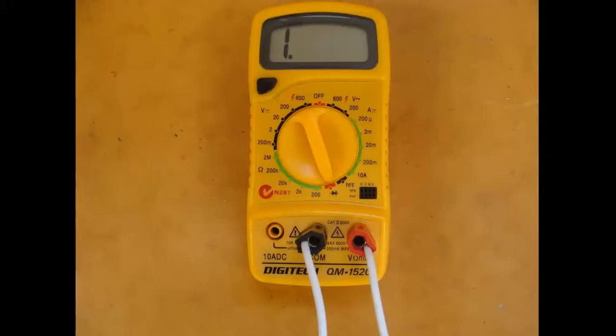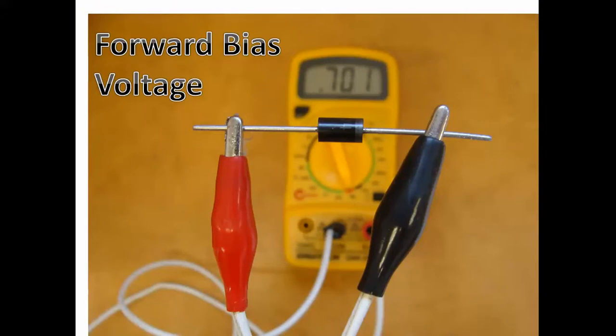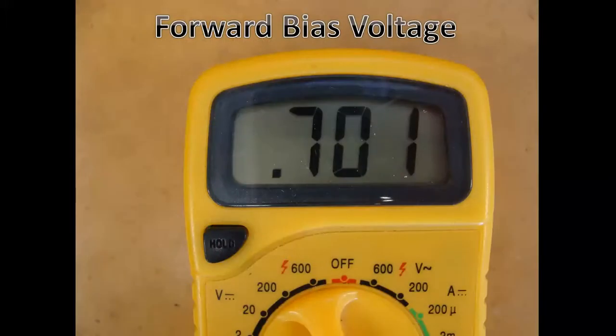We're then going to test the diode using the diode test function on a digital multimeter, and there's the diode symbol at the bottom there. We put the diode in forward bias connection, and we're going to measure the forward bias voltage. Now this voltage that's indicated is the voltage that the diode will turn on at. So this diode I tested turned on at 0.701 volts, which is very, very close to the textbook voltage of 0.7.